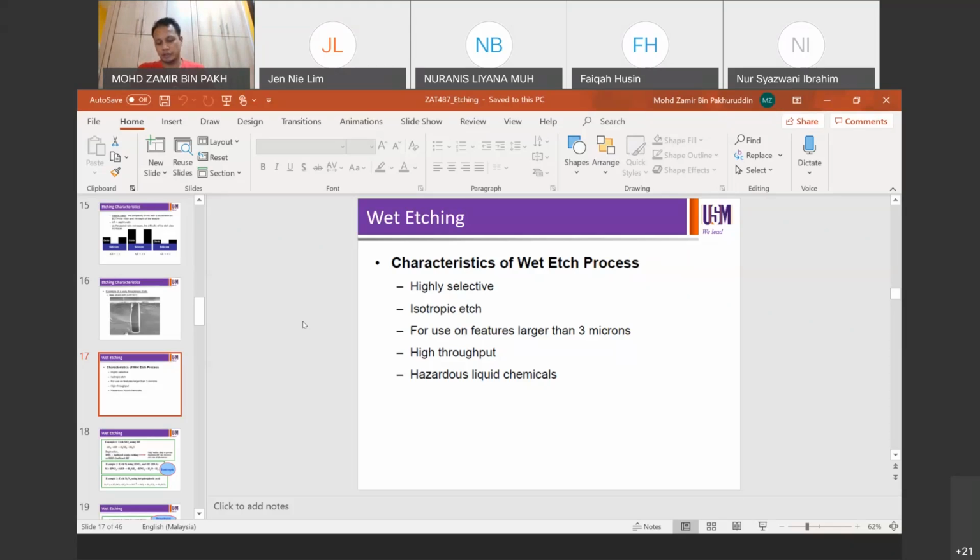For example, in my research, we etch silicon to form nanostructures using wet etch, HF, hydrogen peroxide, and silver nitrate in order to form black silicon, which essentially means an array of random nanowires on the silicon surface where the dimension of the nanowires is somewhere 50 to 100 nm in width.